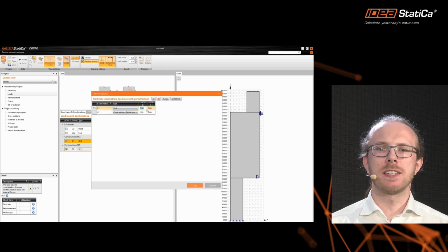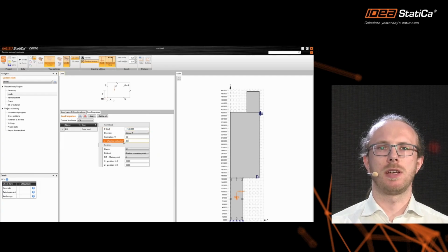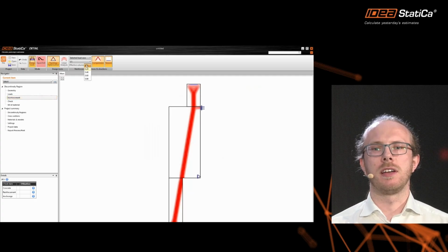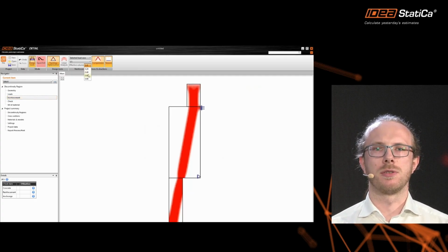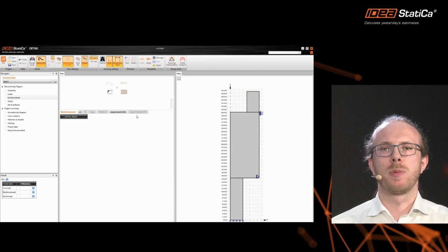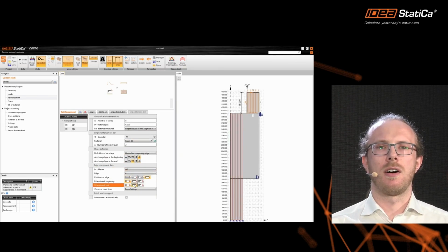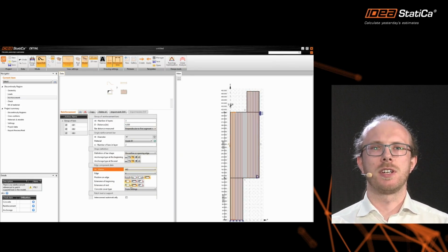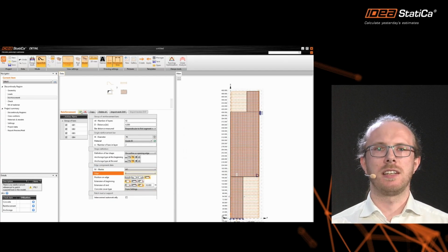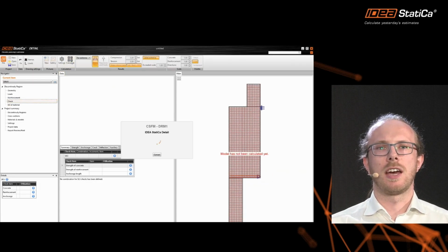So you may have noticed that all of the modeling processes or all of the inputs are done in imperial units, in imperial environment according to the ACI. Here we can see the result of topology optimization, which can be the basis for our reinforcement design, which is again according to the ACI. You can, for example, see the anchorage types, which are brand new according to the ACI.